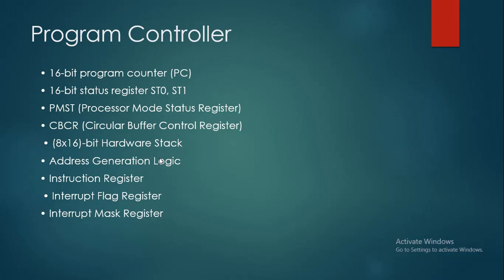These on-chip memories include program read-only memory and data or program single access RAM, like SARAM, and DARAMs. It also has 16-bit on-chip maskable ROM. This ROM can reside both on-chip or off-chip, and it is controlled by the pin called MP/MC bar. If MP/MC bar is high, the device is configured for off-chip memory, and if MP/MC bar is low, the device is configured for on-chip memory.